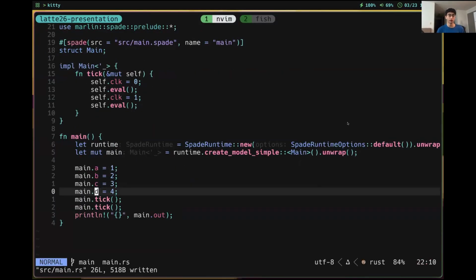In this case, we've done it using a binary. But you can also use it using standard Rust tooling like cargo test, and you can write it with tests because it supports parallel running. And what you should notice is what did not need to happen, which is that we did not need to write a makefile. We didn't need to write a custom Python runner. We didn't need to remember what ports are in our design, which maybe we should, but we could get type level feedback on that.